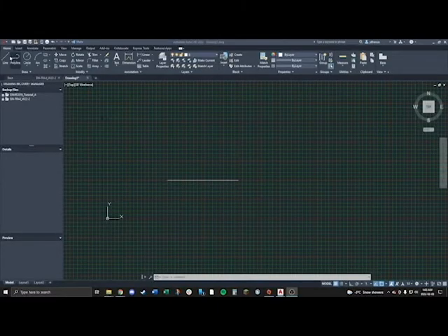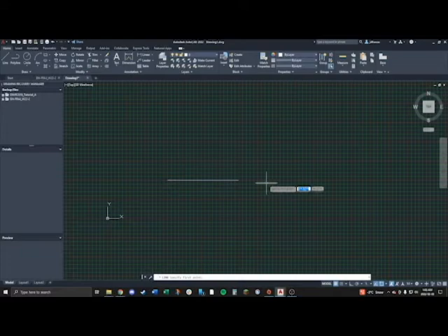Okay, so doing the math on the angle of this, we just covered that it was 35, and then whatever's left is the number we input from 180. So I'm going to start a line, click that endpoint, and input the length, which we were given as 40, tab over, and I know that the angle needs to be 45 because then the interior angle will be 40.